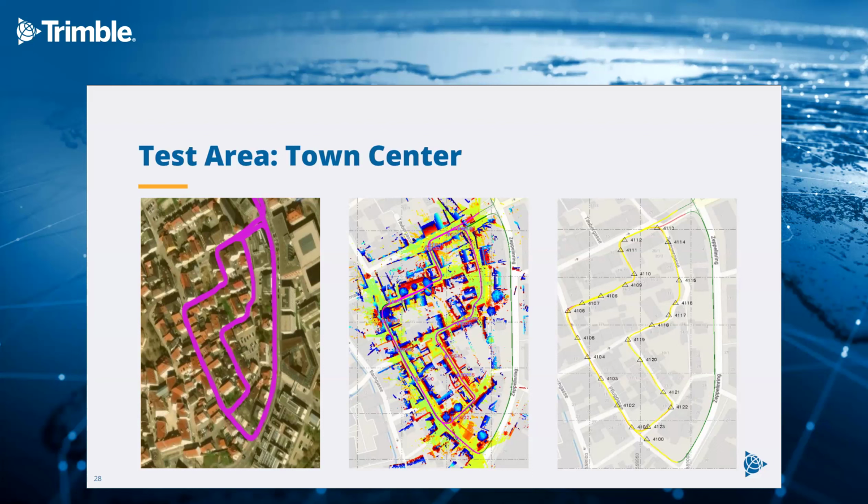And to mitigate any potential datum defects, the same base station with the same coordinates, obviously, was utilized for the ground control point survey, as well as for the GNSS-INS trajectory post-processing, which we did in a single base mode. This is the best approach to avoid any potential datum shifts.